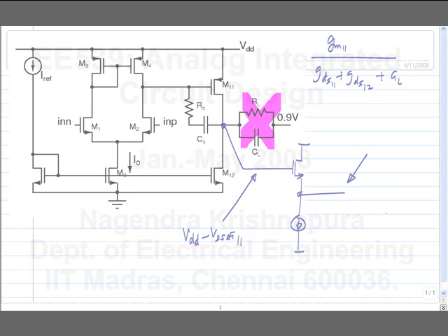You do lose like 1.5 volts in that process, but your supply voltages may be 30 volts, so it doesn't matter. Whereas now you can't do that. So even when you make class B, the original CMOS class B stages were also using source followers, but you can't use it now because it just consumes too much headroom and will not supply enough swing. Okay. So if you are limited by swing, probably the source follower is not a good choice. Okay.